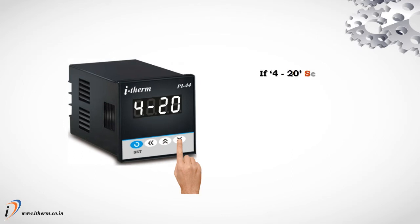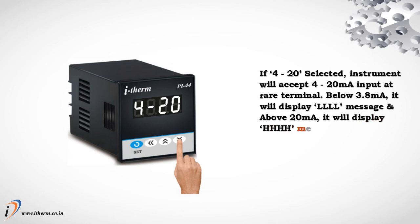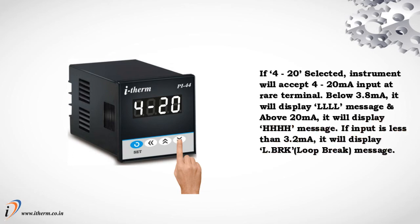If 4 to 20 selected, instrument will accept 4 to 20 mA input at rear terminal. Below 3.8 mA, it will display L message, and above 20 mA, it will display H message. If input is less than 3.2 mA, it will display loop break message.